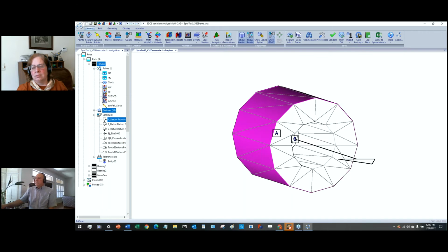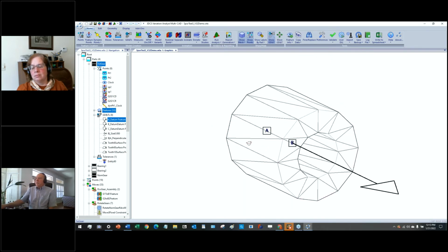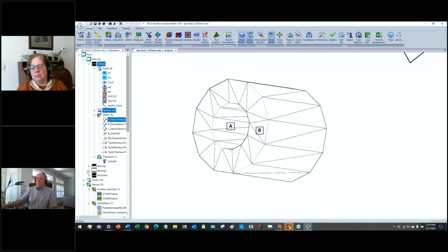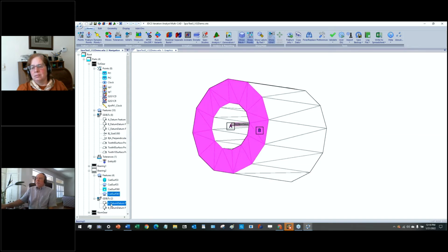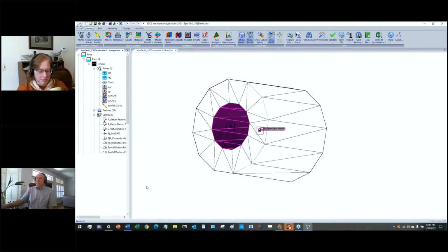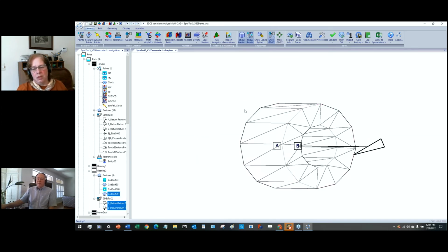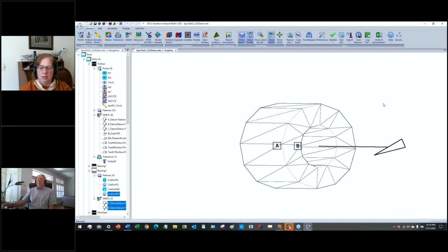In the bearing, datum A is actually on this side of the bearing. If we go to the bearing and the GD&T, that's datum A, and datum B is the shaft hole, not the outer hole. That way we can tolerance the outer shaft and the flat independently of the datums.